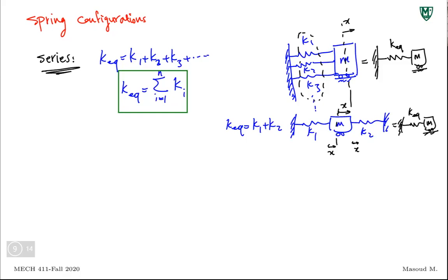Now, the other case, as I said, is very similar to the analogy we use when we're analyzing circuit boards. Springs in parallel. Sorry, I was totally off here. I'm glad I figured that out. This is not springs in series. I apologize for that. This is springs in parallel. Right? For some reason I can't erase this, so I'm going to scratch that. Springs in parallel. I apologize. Whatever I said was for springs in parallel. Springs in parallel have the same displacement.